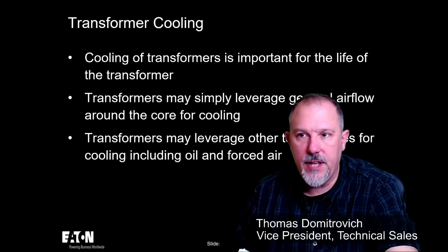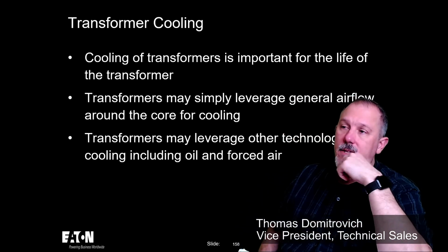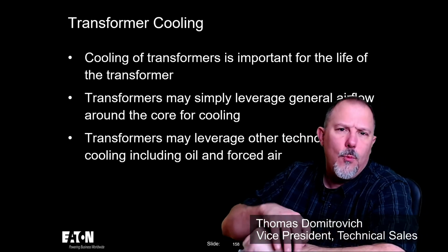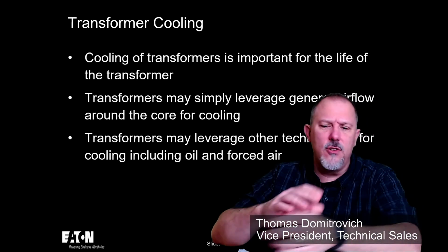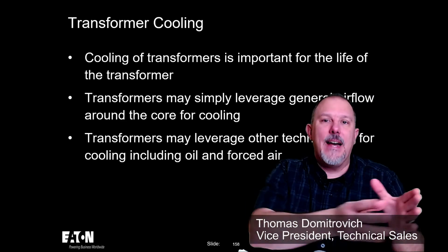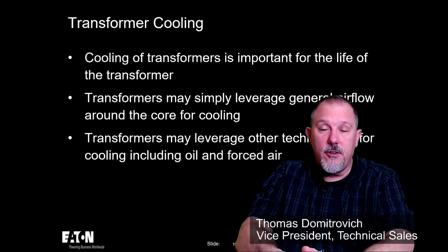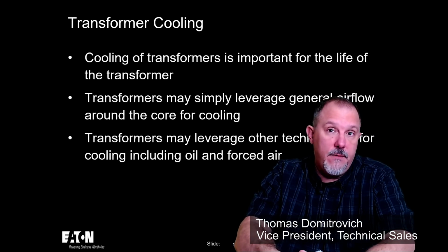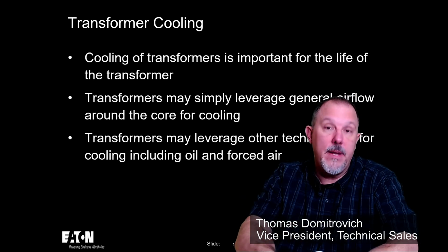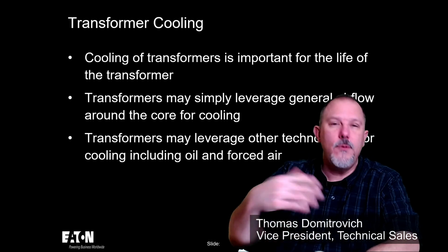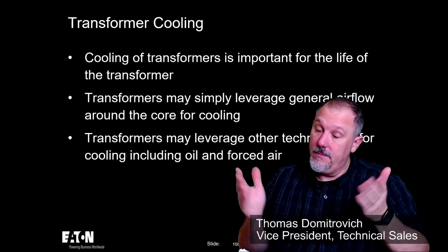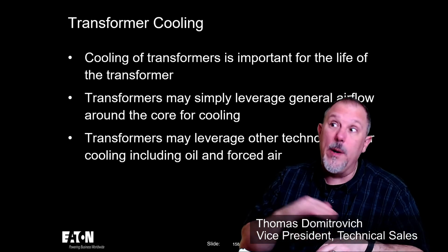So when you look at your load calculations, there's some beef in there. If you look at what we do in North America and even the standards, take a look at an IEC starter versus a NEMA starter. The NEMA starter is a lot bigger than the IEC starter. The NEMA starter gives a lot more forgiveness in various parameters, so you'll get away with making some mistakes and things of that nature. So the load calculations, I think there's a little bit of fluff in there, and it could be that these transformers are nowhere near the loading.